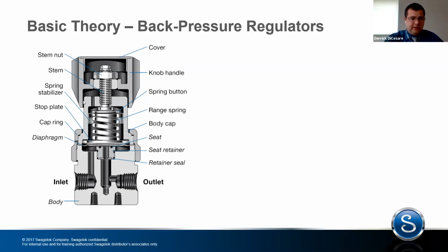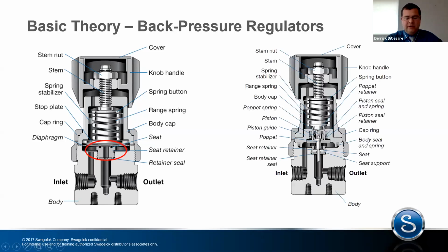Okay, back pressure regulator. So again, it's very similar. It's backwards of the single stage regulator, and you're going to see a lot of similar components. This one doesn't have a poppet. When we get into the higher pressure ones, we do put a poppet in there just to make sure that we do get relative sealing under normal operation. You see a lot of additional components just based on the complexity of how this poppet assembly has to work.